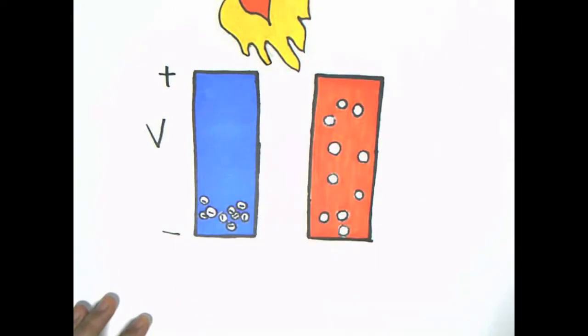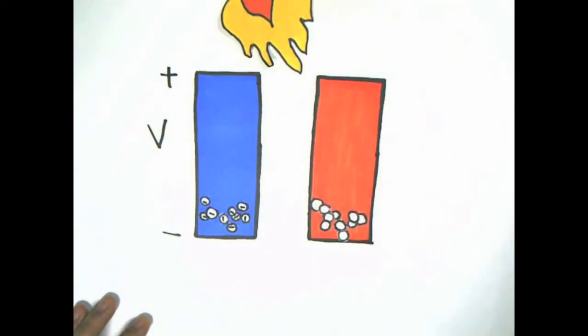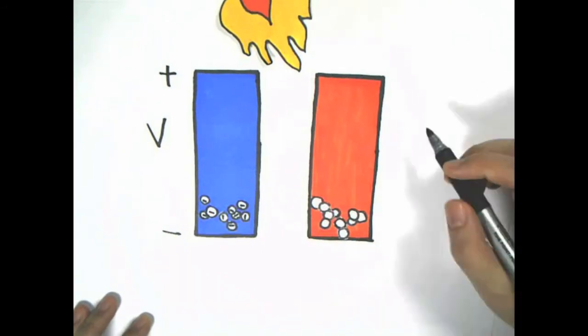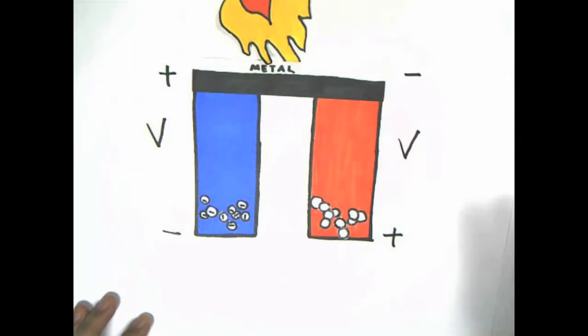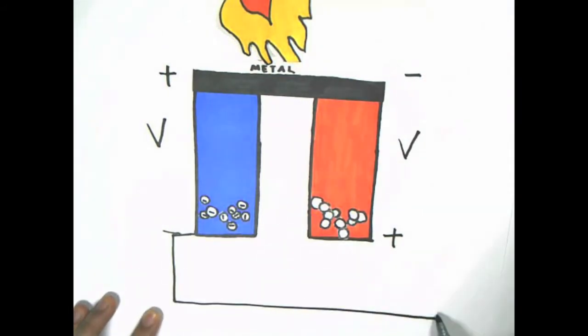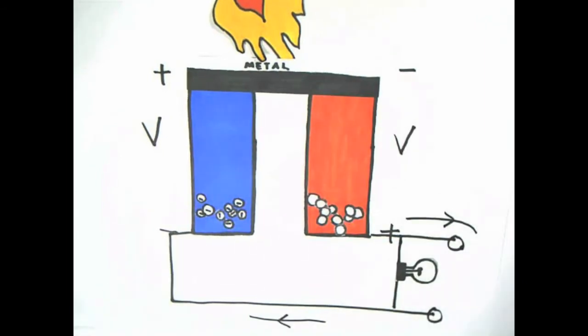The same thing happens in the p-type material to the right, this time with excess holes. Holes will also tend to wander to the cold side, but this time, because holes are positively charged, not negatively charged, voltage is created from cold to hot. Using these materials, we can create a circuit with a resistive load. Because of the thermally induced electromotive voltage, a current will be driven around this circuit. This means that power is dissipated in the resistive load.